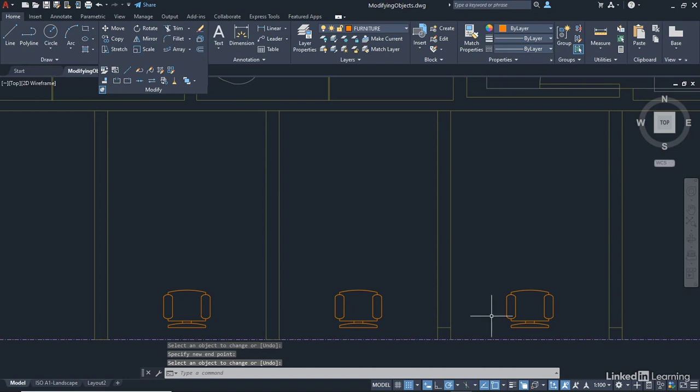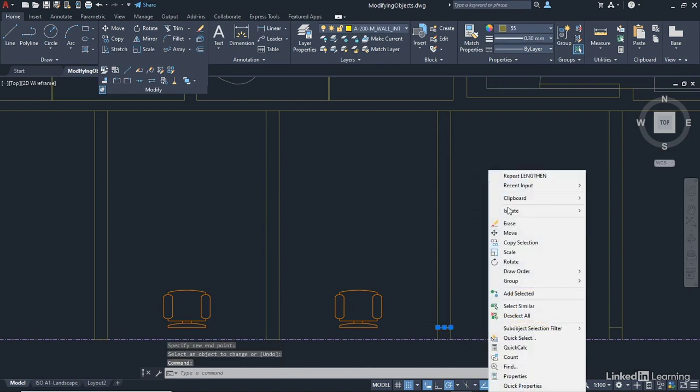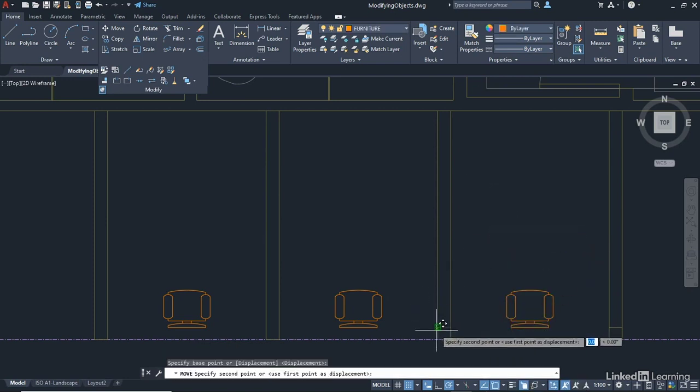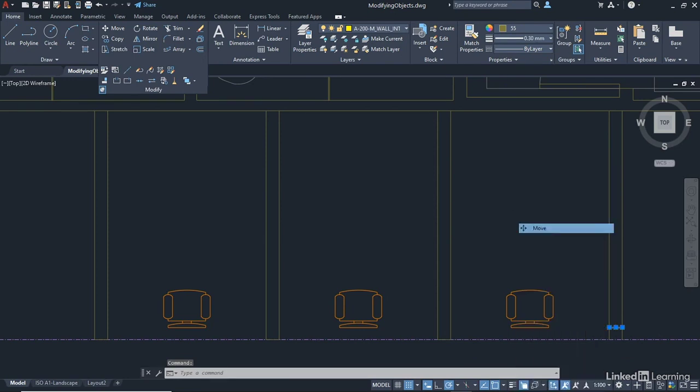All we've got to do now is move our little short lines. So there's our short line there, select, right click, move, pick an endpoint, like that, and it moves. Same again, I can right click, make sure you select the object first though, then right click, move, and it's endpoint. And there we go. We've now moved the ends of our little cubicle walls there down to the grid line to allow the guys on site to measure straight off grid when they're adding those internal walls for the construction of the building, of the floor from our floor plan.